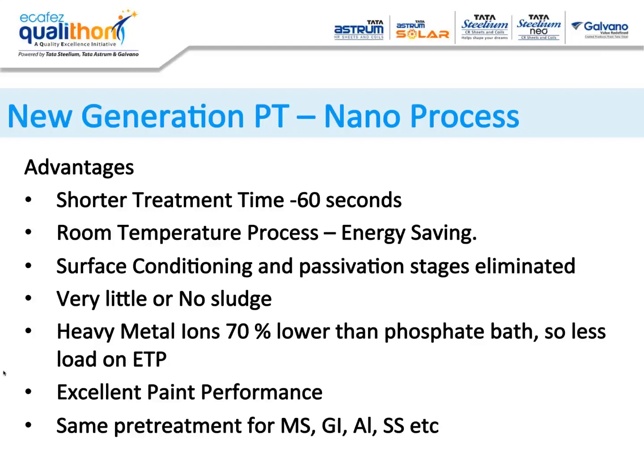Surface conditioning and passivation are not required in this, which is another beauty of it. You don't need passivation because this is not crystalline, this is amorphous, and you don't need surface conditioning. Then there is very little or no sludge. One of my customers is running a plant where, in 6 months, when we clean the filters, the entire sludge we generate is not more than 2 to 5 kgs. So you can definitely say very little or no sludge.